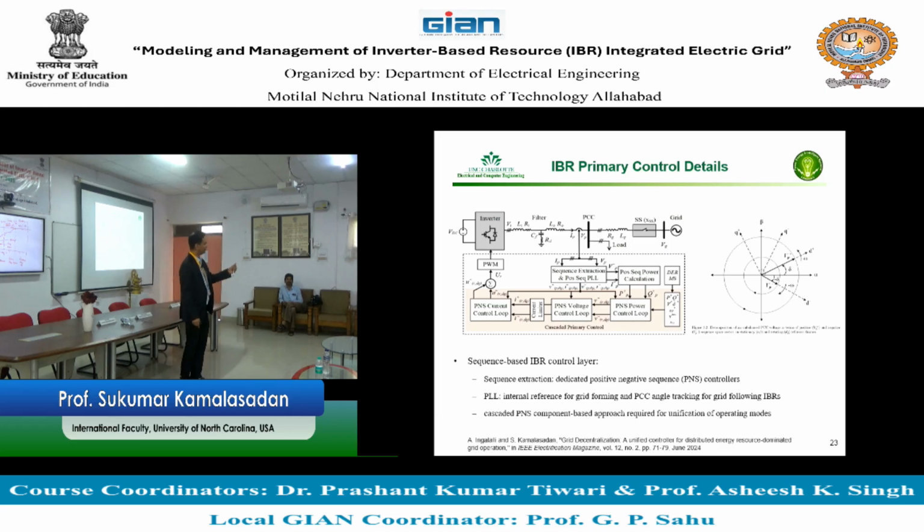So the fault current is drawn by the fault, which means the nearby voltages which are giving this current start dipping. And if it is a fault which is bolted on the bus, I think we talked a little bit about bus fault, this voltage will completely collapse, right? You know what a synchronous generator does? A synchronous generator will hold this fault current because of the inductor and the winding sitting there. It's not going to release the current. All the current which has been drawn from this winding, because of the storage capability, it stores in the winding and then releases a little bit later. So the fault current is not shooting up very high.